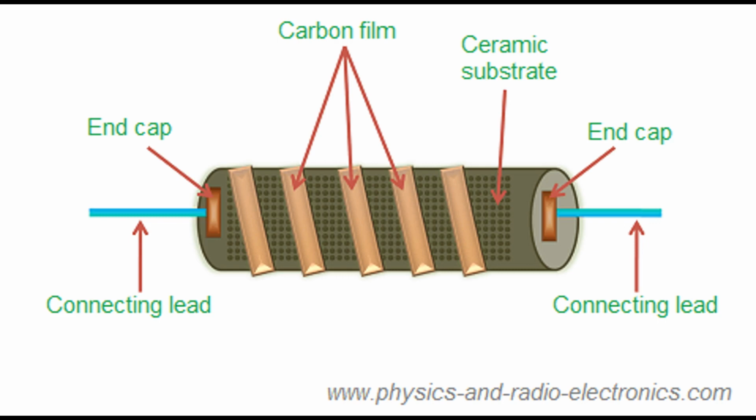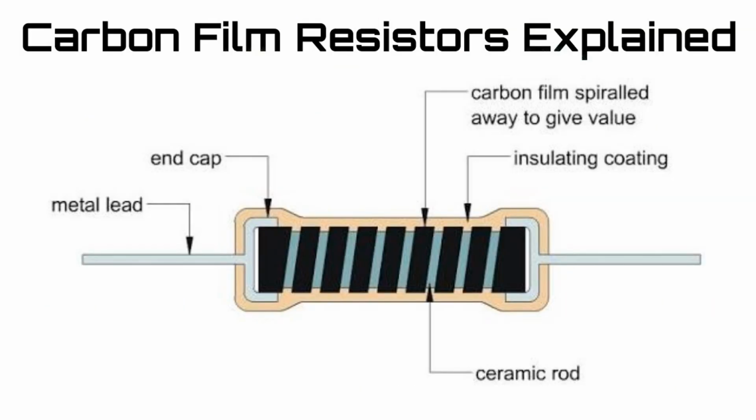Pull-up and pull-down resistors. These are used in digital logic circuits to establish default logic levels for input pins and prevent floating inputs. Noise reduction. Resistor networks and damping resistors are employed to reduce noise and interference in electronic circuits. Voltage clamping. Zener diode voltage clamps often use resistors to limit current flow when the voltage exceeds a certain threshold. Current measurement. Precision resistors are used in current measurement circuits, including shunt resistors for current sensing.